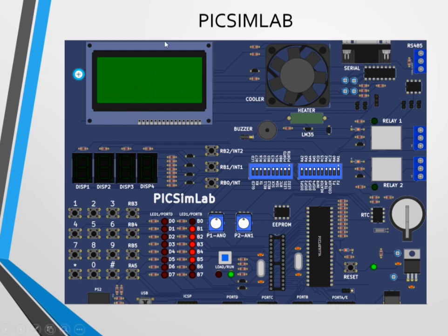Next, this one. This is nothing but the CLCD, character liquid crystal display, where we get the display on the screen. These are most commonly used to display ASCII characters. And in the screen, some customization is possible. There are two communication modes, that is 8-bit mode and 4-bit mode.